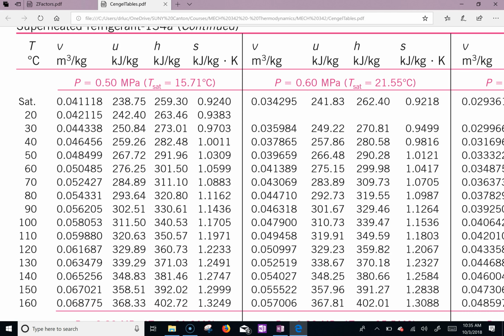This temperature right here is that temperature. Then these are the temperatures on the left; they're not saying they're saturation temperatures. So right here, and our temperature was 90. So this whole row across, and boom, that's our volume right there. I hope that's what I wrote down. Yep.